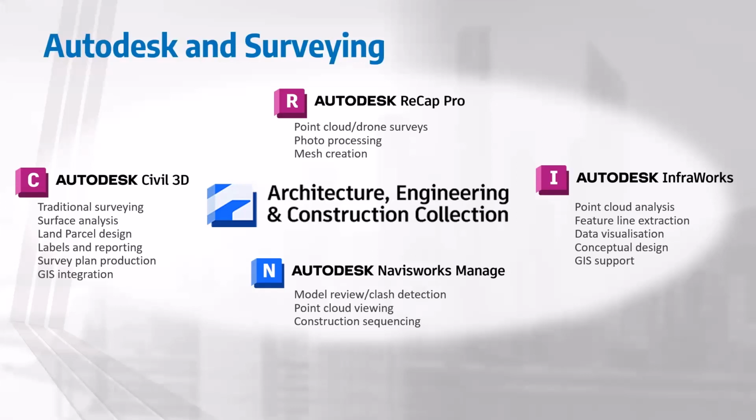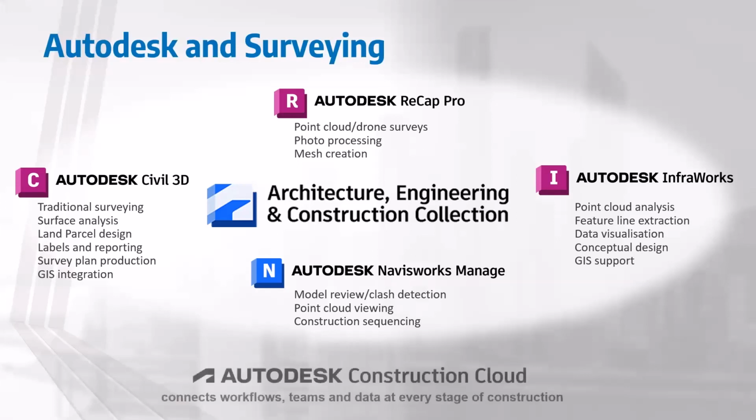The Navisworks Manage is listed there because if nothing else, it does an amazing job at clash detection. So if you've got data, say a wall, and then point cloud data or point data you've picked up, you can basically check offsets of that data from the wall and make some assessments there. It's also great for construction sequencing.